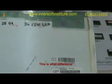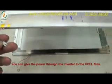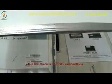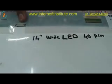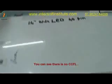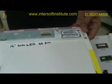This one is different. Here you can see it is a CCFL connection. You can give the power through the inverter to the CCFL. CCFL will be inside of this LCD. In LED there is no CCFL connection. For CCFL this is a different connection from LED power. In an LED LCD there is no CCFL power connection. You can see there is no CCFL. Only the bulb will be here on the LED connection, and it is a 40 pin.